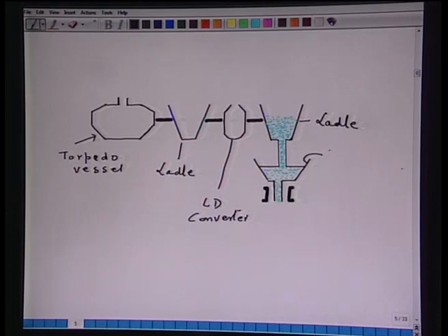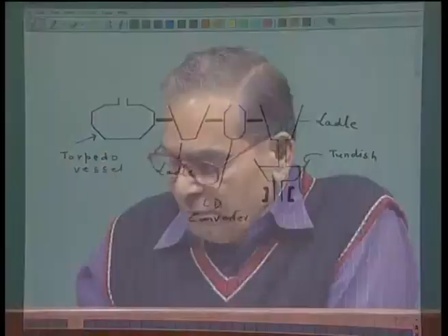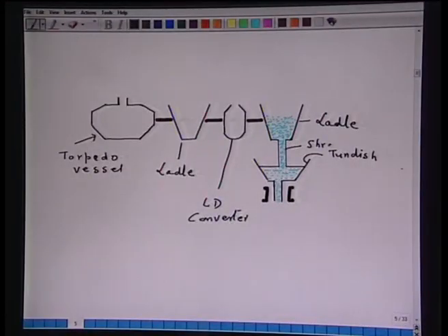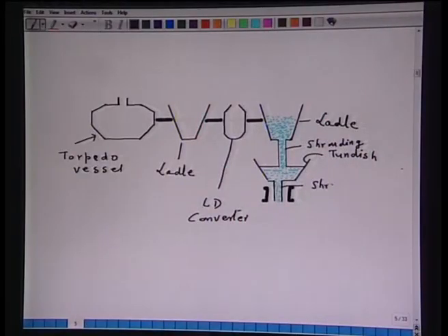and this is a tundish of a continuous caster where refractory materials are also required. This is the shrouding of a falling liquid steel stream, there also refractory material is required. This is again a shrouding of liquid stream that is poured inside the mold. So, these are the various areas or various vessels that require the refractory.